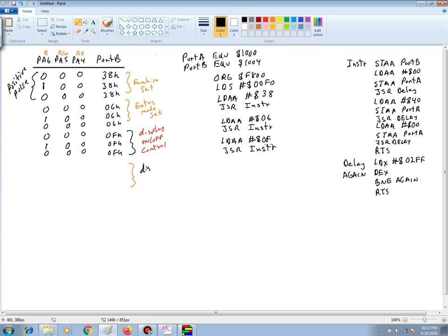So display clear, and then we need to send a 01 hex, right? And we need to do the enabling as well, where they're all lows. Then the enable line goes high, then it goes low. All right. Now this did get a little bit skewed here. Let me pull this up just a little bit, somewhere there, a little bit better.